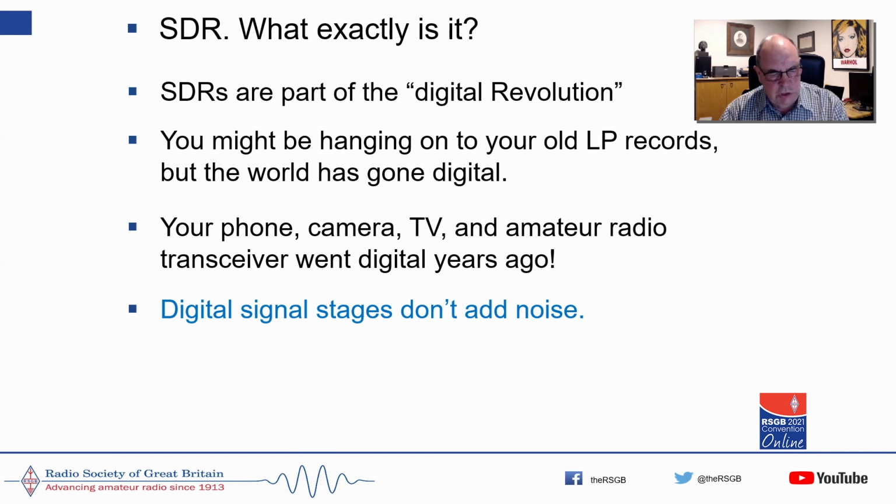So you can regenerate a noisy digital signal into a clean digital signal, and you end up with a nice clean system. With any analog transmission system, every time you amplify it or send it across the airwaves and receive it at another site, there's noise added, and you can't get rid of that noise easily.